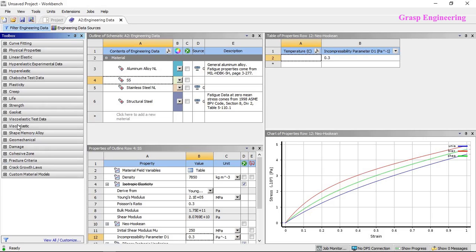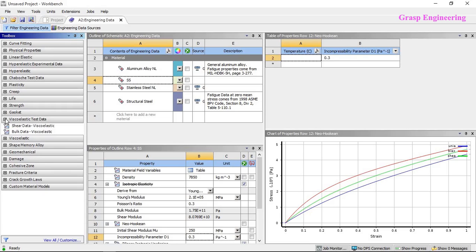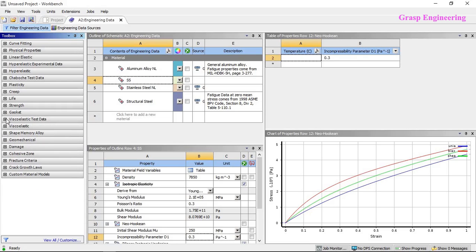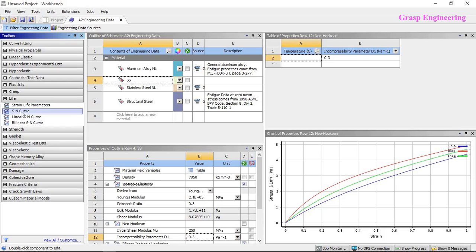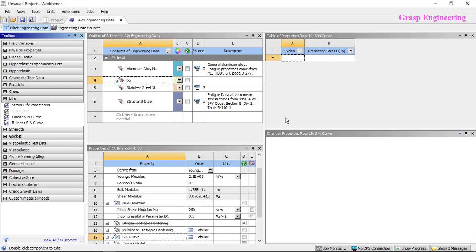Now damage and these additional things are there which are basically for other simulation types. Like when we talk about fluid structure interaction, in that case we will need all these details. And if you have fatigue, then in that case you just need to define stress strain curve. So here you just define the stress versus your strain curve, okay, from here.